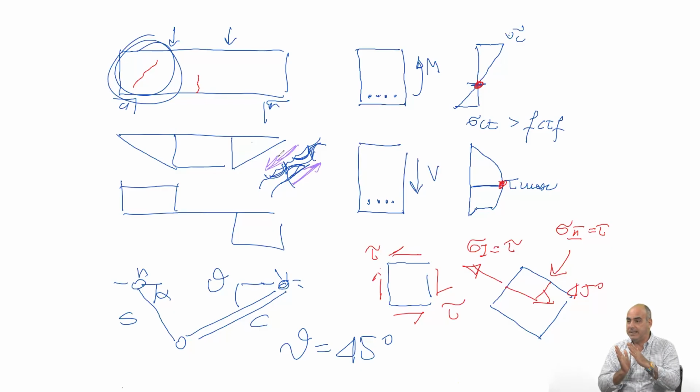And these forces sum up to the compressive force in the strut. So it's not only the truss mechanism, you have to add additional forces. So if you have a force in this way and you sum up another force like this, your resultant will be a force which is less inclined.